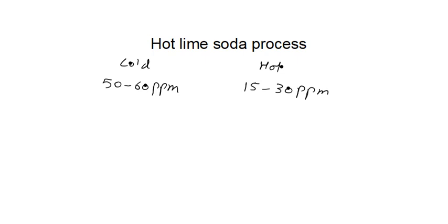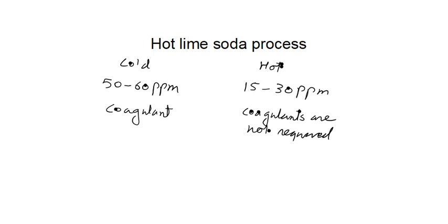The outcome is better. In cold lime soda process, the coagulants are required, whereas in hot lime soda process, coagulants are not required, because the accumulation or growth of particle takes place at high temperature.